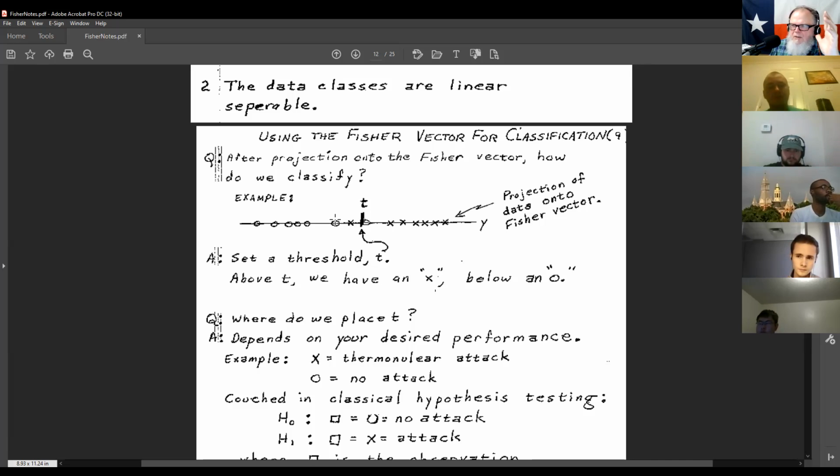This is inherent in all detection design. As the detection probability goes up, the false alarms go up. It's a classic trade-off, and you can't have both. What you would like is to have the best decision that you possibly can, but this can be viewed as follows. As the T changes, the false alarms and the detection probabilities change, don't they? At this T, there's going to be a certain detection probability and a certain false alarm probability. As I move it over here, they are going to change.